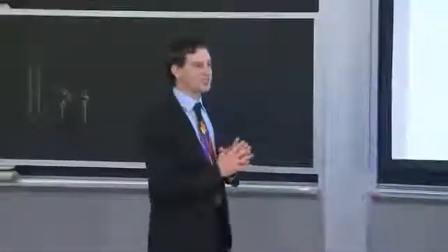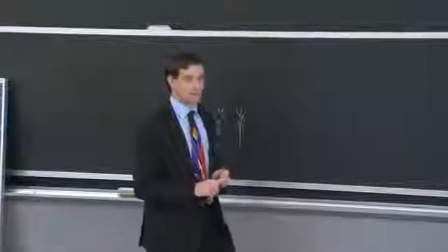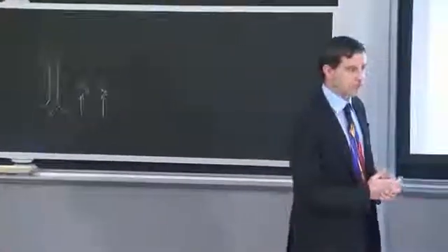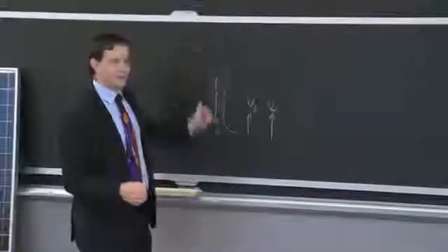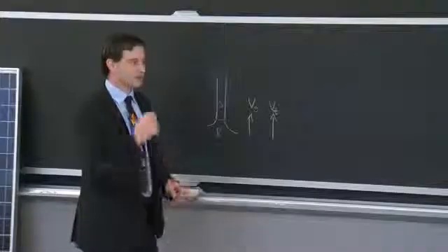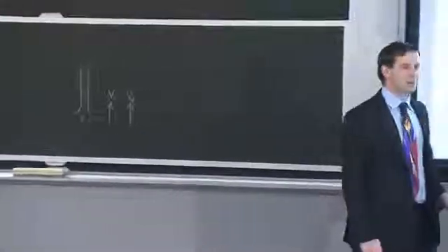You can use your imagination. But ultimately, growth continues in air, and you're limited to, at most, around 5 centimeters per minute growth velocity because of the extraction of latent heat. If you try to grow faster than that, you'll eventually just pull the solid off of the liquid. It'll dissociate much like pulling an ice cube off of the top of a glass of water. Right? Surface tension won't be able to hold the two together.